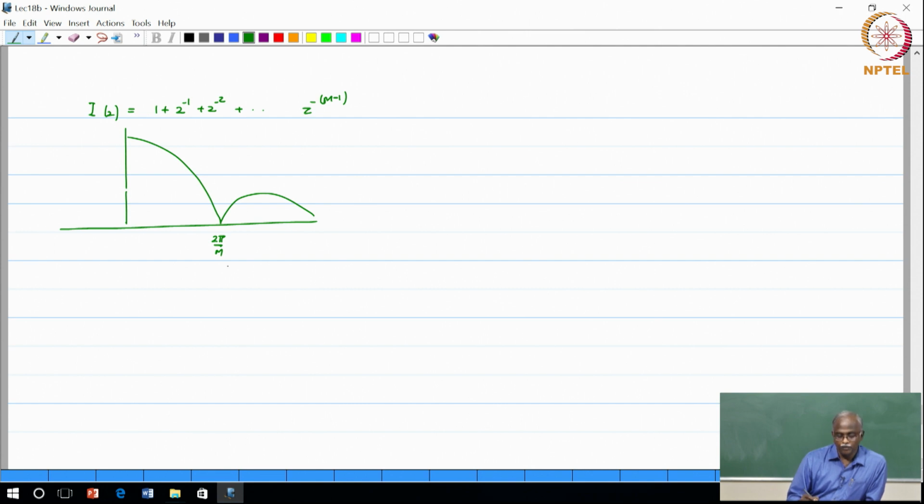Okay. Now I can design this filter such that I get a 0 exactly where I want it to kill the response, right. So, that is one observation. So, let us say that I did h naught of z power 8, that means I will get 7 images and I will choose m equal to 8 and I will basically kill all of the unwanted images by placing an exact 0 at those frequencies. Am I right? Okay. Are you satisfied with the design?